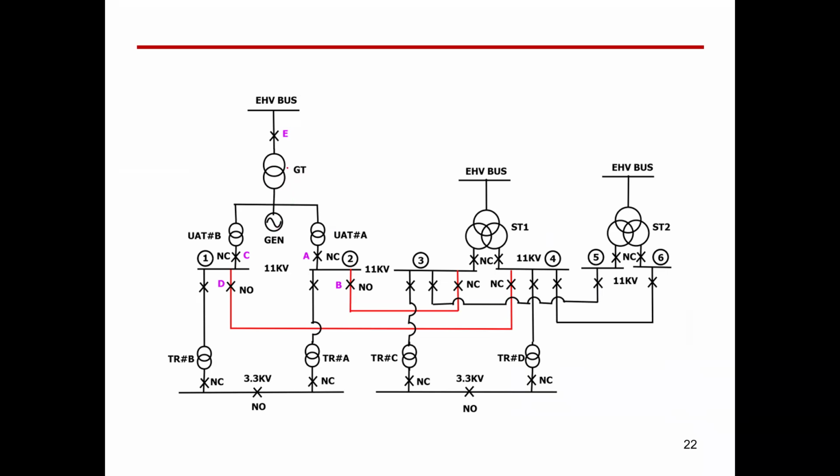Sometimes, guys, you may find this symbol here, these 3 dashes, which means this is repeated 3 times because this is a three-phase system. So this is called a single line diagram, but we have 3 of this one. Or sometimes you can find it like that, just 1 dash and written here 3.